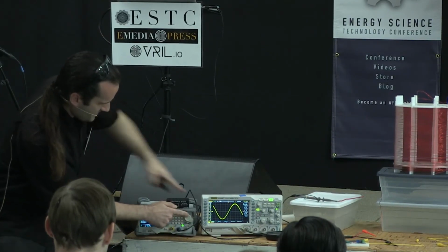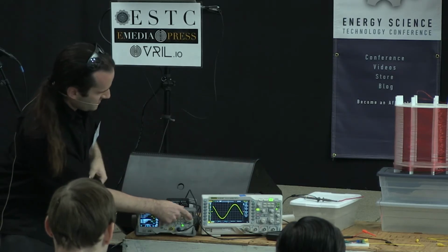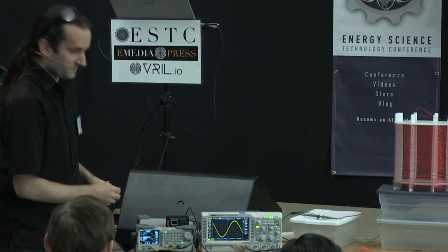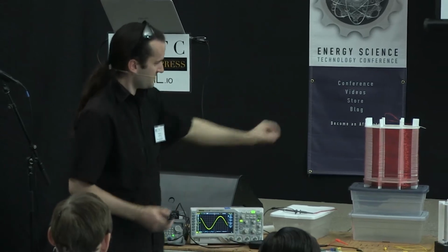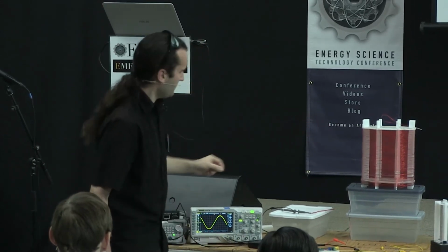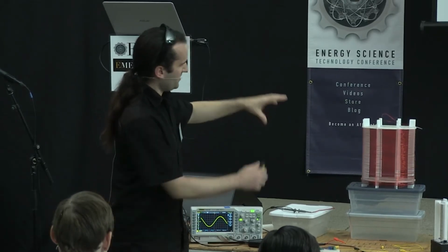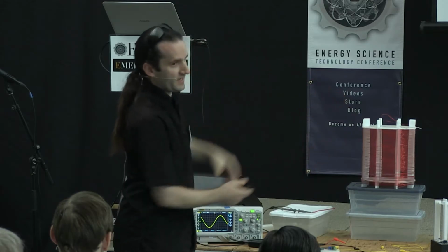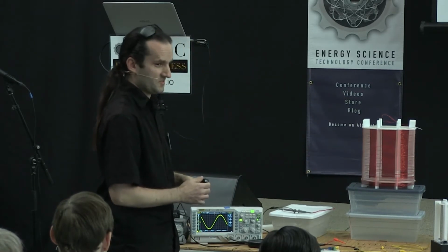If I tune the frequency up, you can see it comes up and down, and that's the oscilloscope probe picking up the dielectric field that's expanding into space here. So not only is there a magnetic field running through that, but because there's a spacing between the wires, there is a dielectric field that is built up from here. So the coil is resonant in the dielectric field. The spacing allows it to expand out into space. So essentially the whole region around here is part of the circuit.